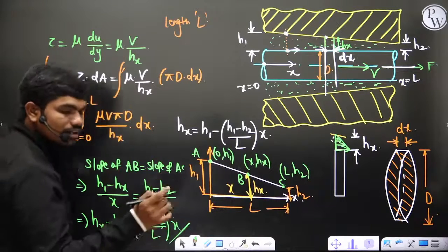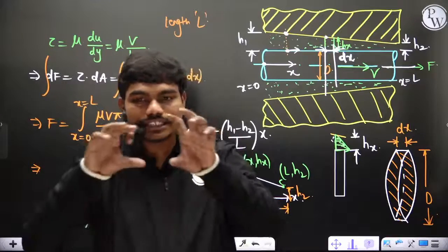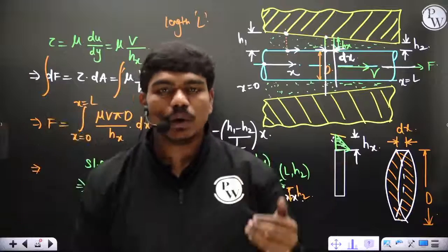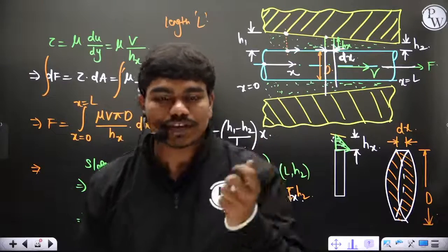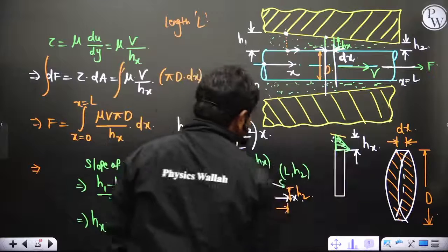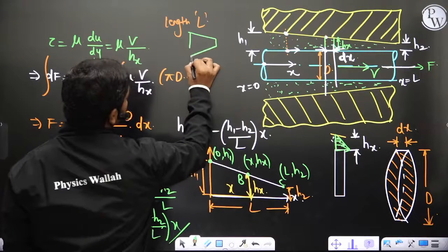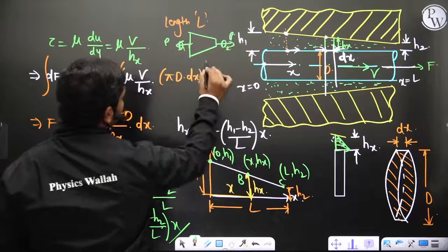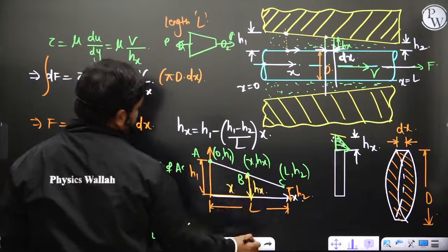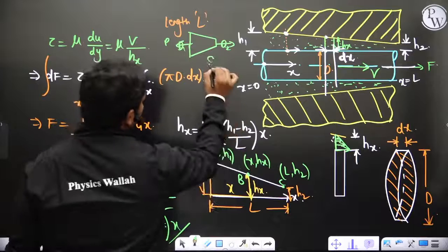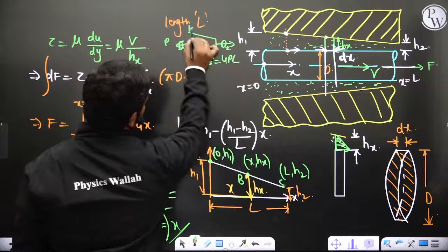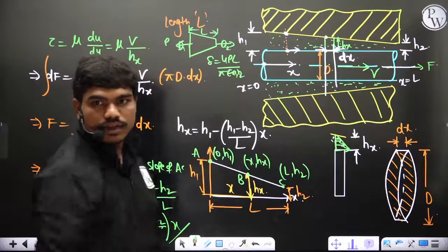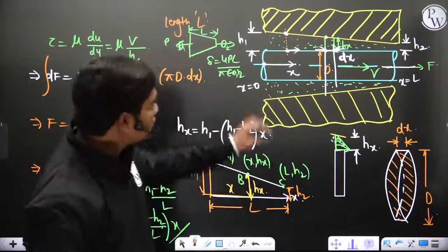This question you also have done in strength of materials. You might have seen there is a tapered shaft from diameter d1 to d2. There is an axial load applied. What is the elongation in the tapered bar? You might have done this question. So there is the same situation like this. You have a shaft from diameter d1 to d2, and if you apply a load P, then definitely we will see delta is equal to 4PL, if this is length L, then pi E d1 d2. You might have seen this, something like this. Yes or no?